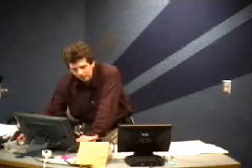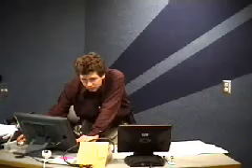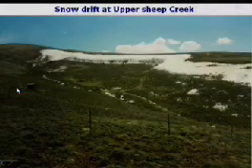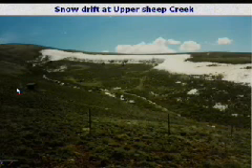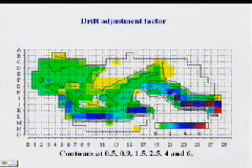And we'll take the measured precipitation. If you look really carefully, there's a rain gauge somewhere in here, a shielded rain gauge that measures snow accumulation. We're assuming that the snow that accumulates in the drift is a factor multiplied by what's measured there. And these were the factors that we were able to come up with by basically comparing the measured rainfall to snow measurements on the ground.